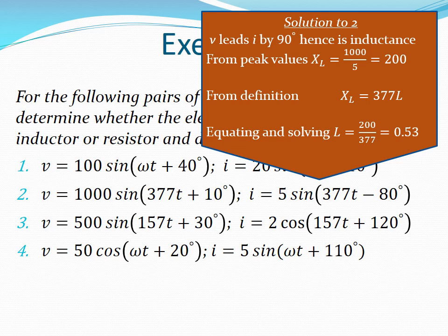From the frequency and the inductance, we can also determine the magnitude of the reactance. In this case, we obtain it as 377 L. Let's equate the two values and solve for L. We obtain the inductance as being equal to 0.53 henries.